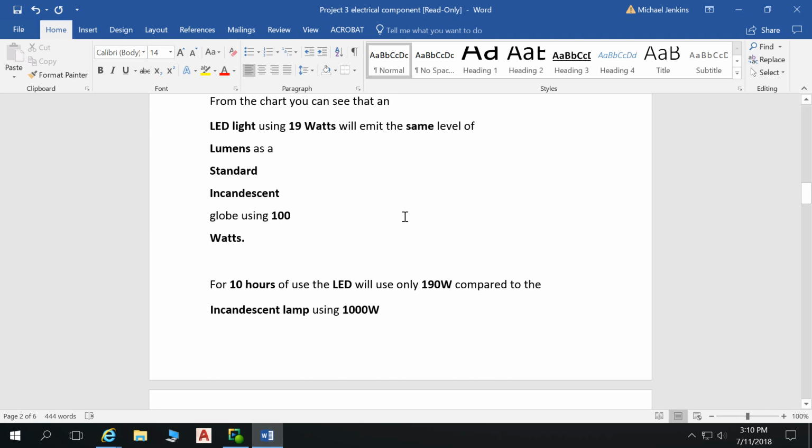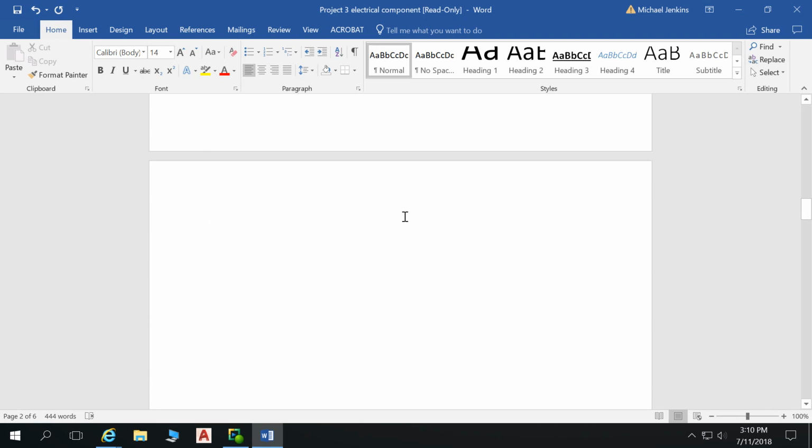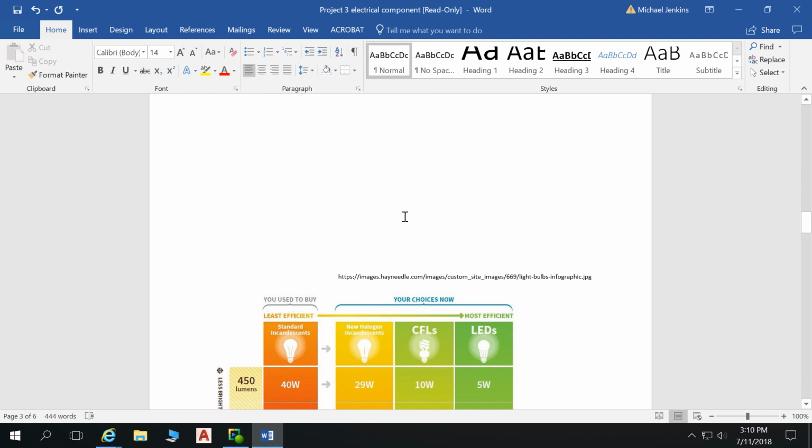By all means, do that if you wish, but it's about finding lights which will fit into your grid type ceiling. So I suggest having a suspended ceiling with acoustic tiles in those 600 by 600 grids, because this is going to be the simplest for you, and it's a very common ceiling system for an office situation.